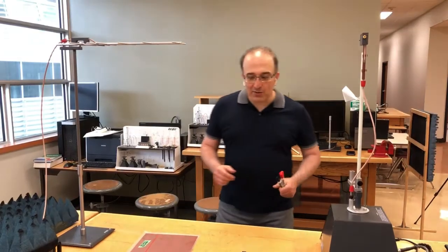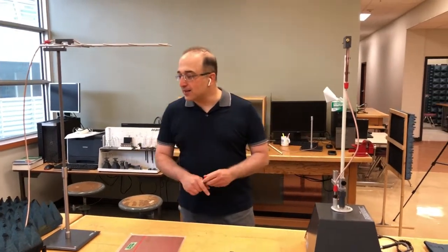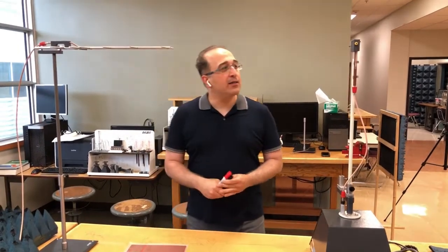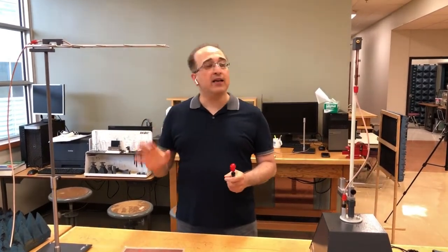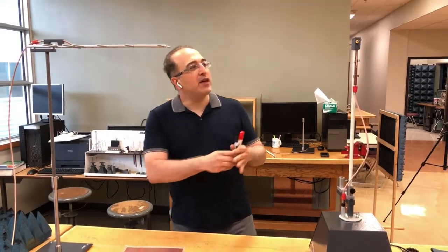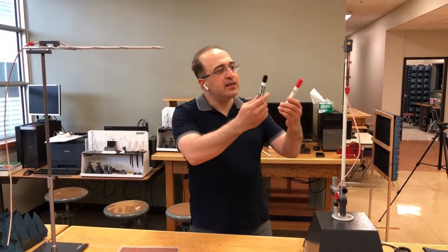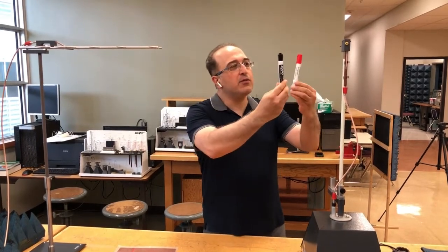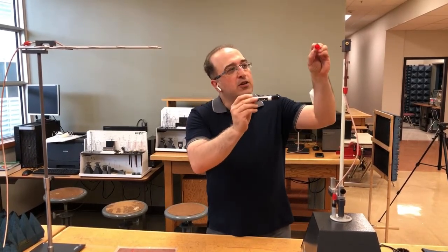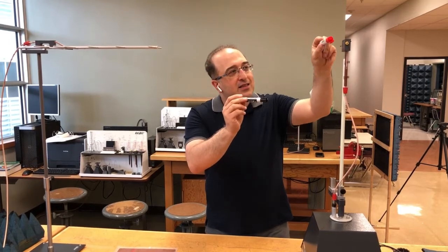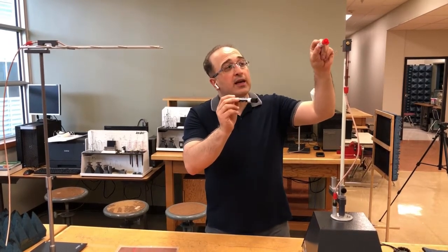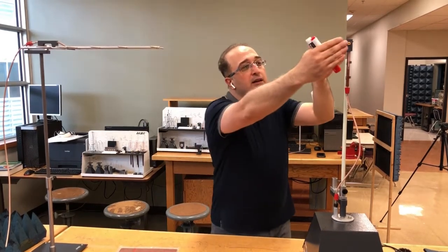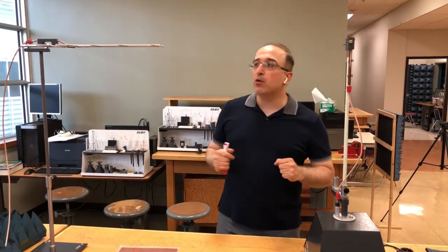In the experiment that we performed with the LabVolt antenna training system, we used this Yagi-Uda antenna at about 1 gigahertz to create a local plane wave at the antenna under test, because this is supposed to be tested in the far field. So if you think of this as an electric field, you need to have an electric field that's relatively uniform in amplitude, phase, and polarization over the area of this dipole antenna.